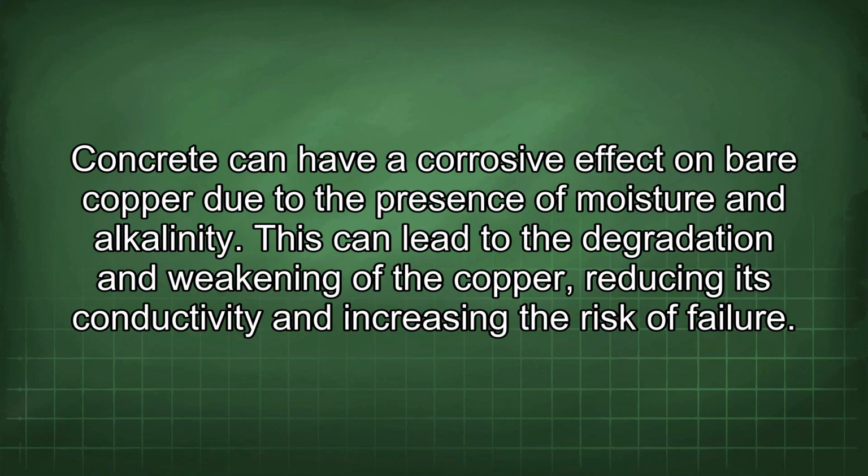Concrete can have a corrosive effect on bare copper due to the presence of moisture and alkalinity. This can lead to the degradation and weakening of the copper, reducing its conductivity and increasing the risk of failure.